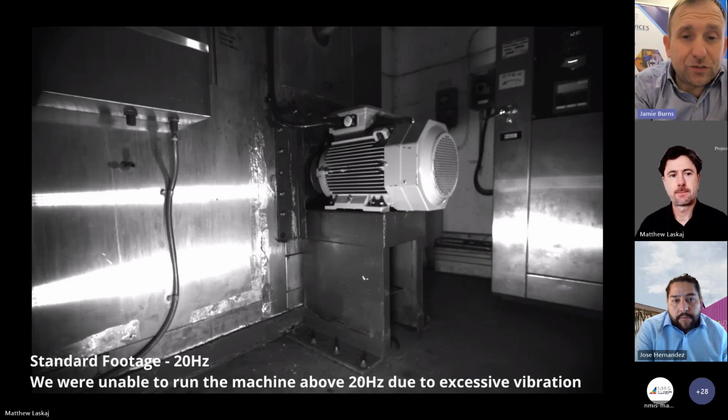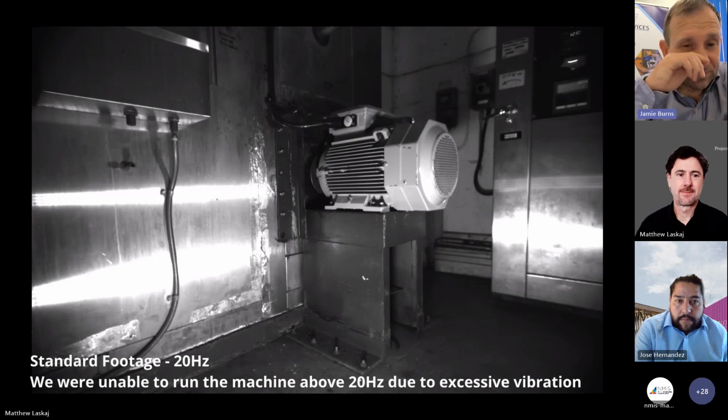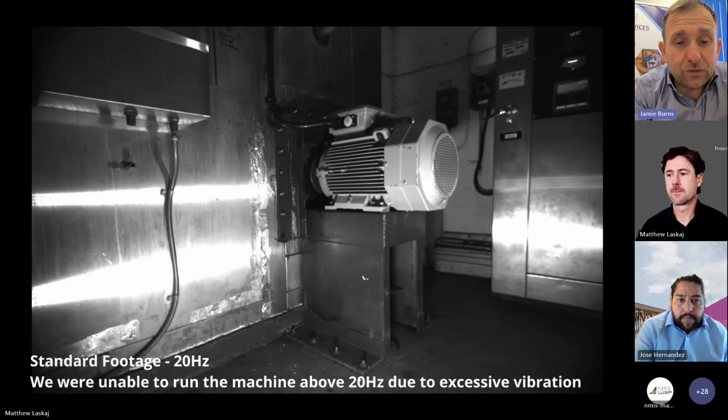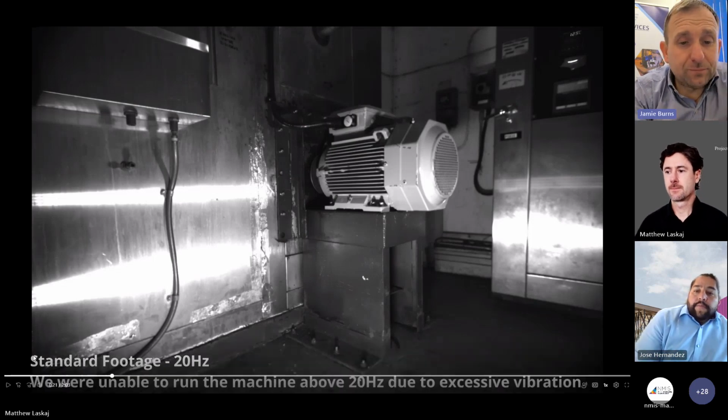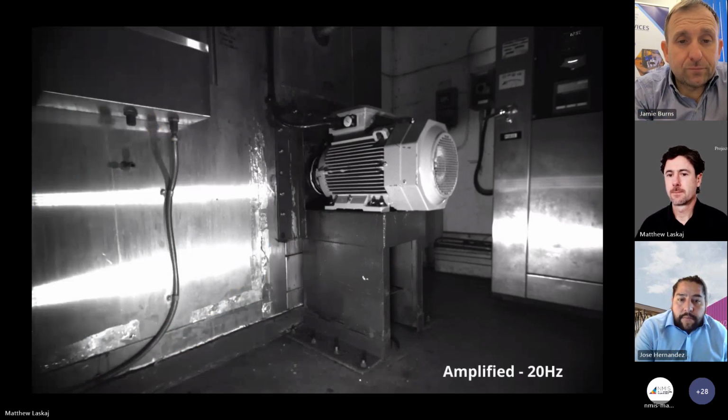So much so that the engineer who was there, and who's been around lots and lots of sites and standing next to lots and lots of machines that are moving around, says that's the worst one they had been to. So the first thing we did at that point was say, right, we'll get the motion amplification camera on this, because there is something else going on. So this is it, just running at 20 hertz. If you just press play again, and you can see it's already rocking.